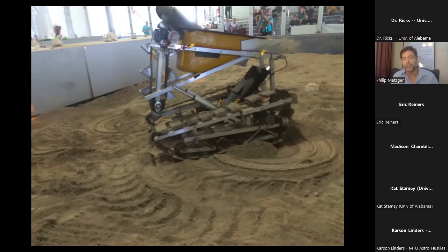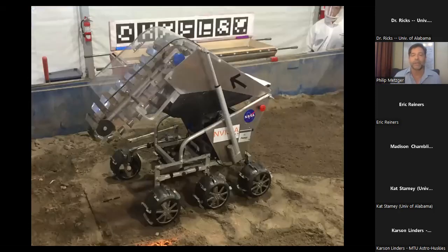And what you're doing is you're skidding your wheels sideways, left and right, across the soil, and that digs dirt into the sides of the wheels, which creates additional friction and resistance to travel. And this could cause what I call an initiating event. Whenever a vehicle gets stuck, there's usually an initiating event that precipitates a chain of reactions that ends up being stuck. I'll say more about initiating events a little bit later.